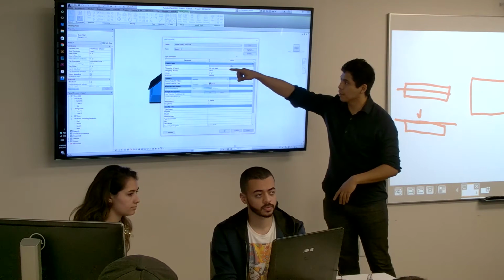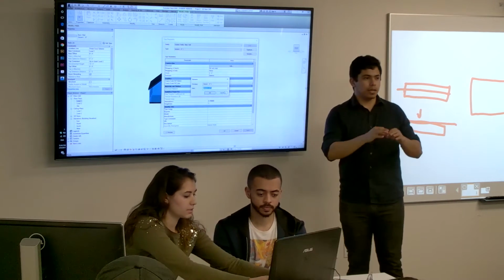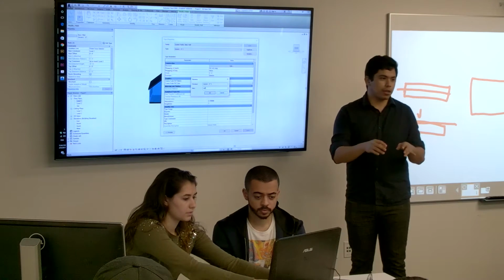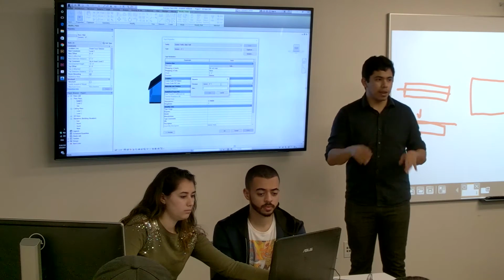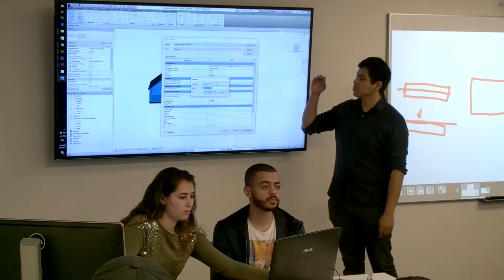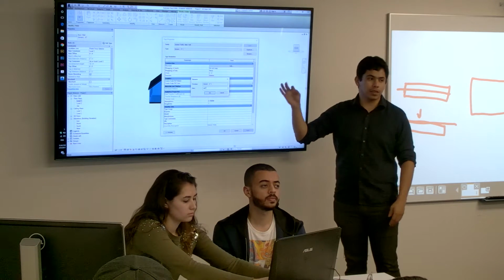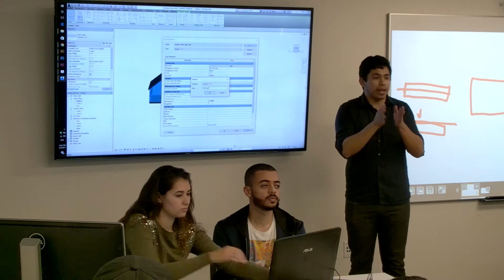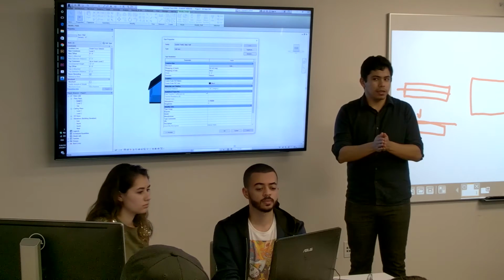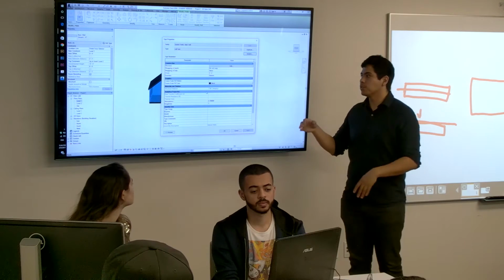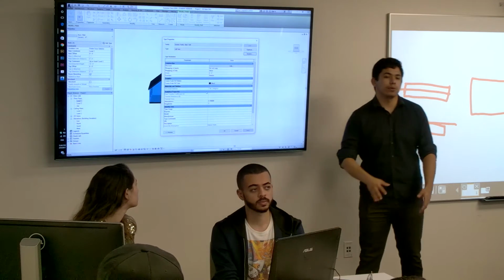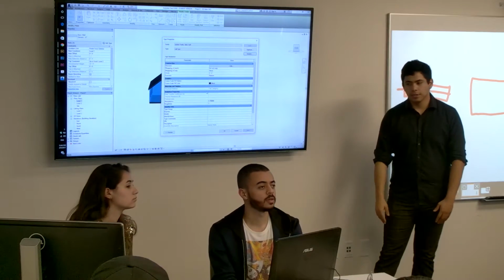So this is called generic 8-inch. Make it generic 8-inch with copper exterior, or with wood panel exterior. You never want to work on the last one, because you are working on that family. As an aside, always work on something that's duplicated. You never want to work on what Revit gives you.